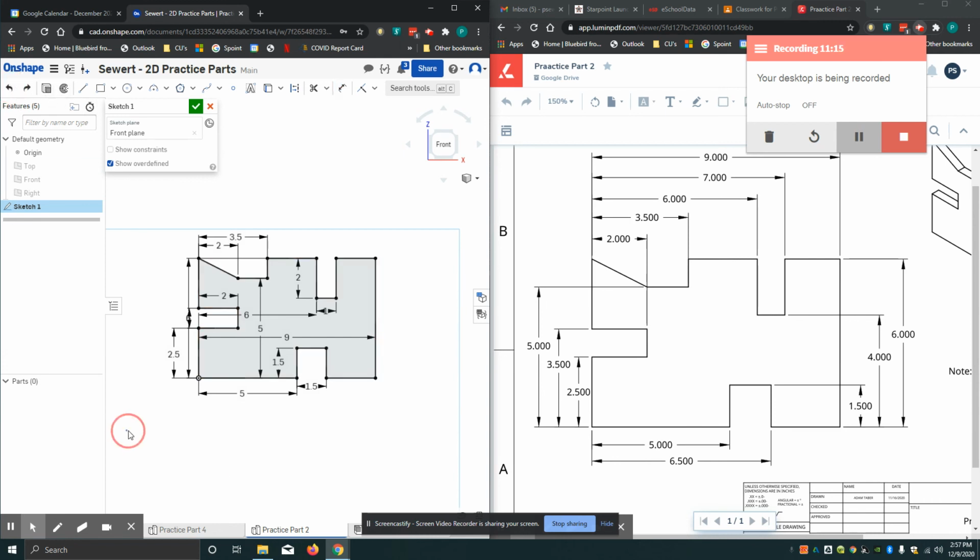Let's see what happens when I do the 9-inch one. All right, dimension tool. From here to here, 9, hit enter, and that one's gray also. So that means that, oh, here's the dimension right in here. So I don't have to have this one either, so I can undo it. Okay, so my part's good now.